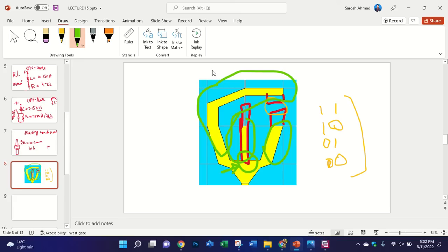So if I have three frequency bands, it means I can vary the frequency bands, or I can make it frequency reconfigurable. Like I can use diodes at these points, at the lower starting points, so maybe it will become a frequency reconfigurable antenna. So you need to think multiple times about your design. You don't say that I have created the shape, I used the diode and it is not working. Every design works, but you need to find the exact position of the diodes. Did you understand what I mean?